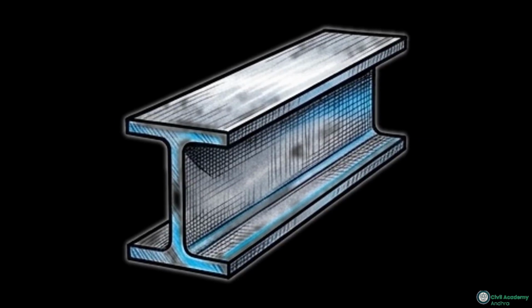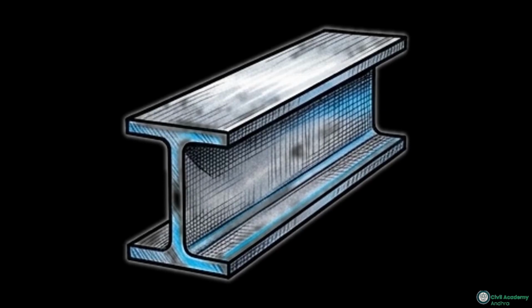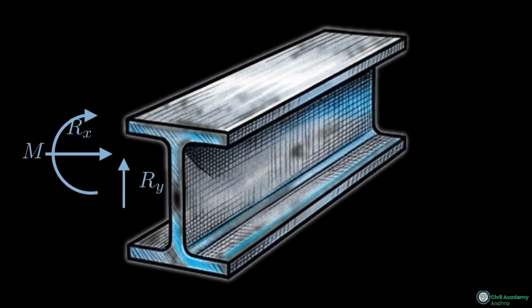Take this roller support as an example. It allows the beam to slide horizontally, but prevents it from falling. Because it only restricts vertical movement, we represent it as a single upward reaction arrow. A pin joint is more restrictive, blocking movement in both horizontal and vertical directions, which requires two arrows. A fixed support goes further by preventing rotation entirely, adding a third curved arrow to represent the resisting moment.